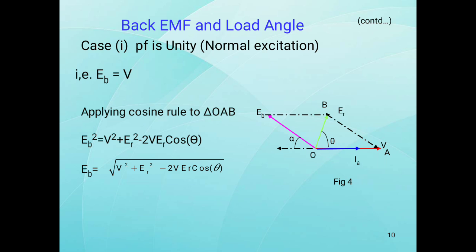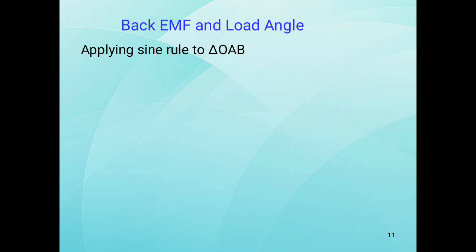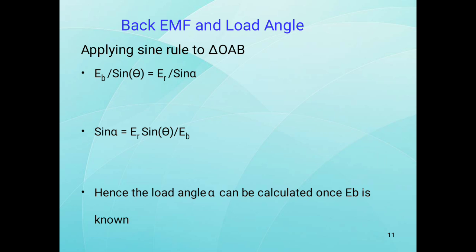This is the formula for back EMF. Now for the load angle at unity power factor under normal excitation, EB by sin theta is equal to ER by sin alpha, so sin alpha is ER sin theta by EB.